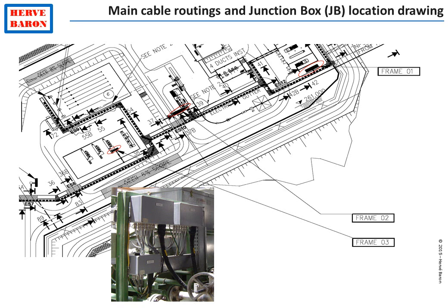The allocation is done by type of signals. There are some junction boxes for analog signals and some others for digital signals. And also, there are junction boxes for the process control system and some others for the process shutdown system. The allocation of instruments to junction boxes allows to specify the specific type of hardware that will be required for the control system.